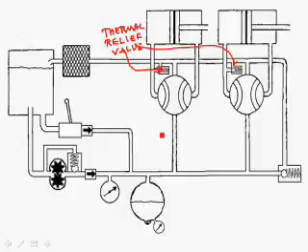Let's say that we park the airplane and these selector valves are in their current position and this is off. So no fluid can go through here, none can go through there, none can go through here. Well, just because hydraulic fluid is not compressible does not mean that it can't expand and contract with temperature. Let's say that it starts expanding because it's sitting on a hot ramp on a hot day in the desert. So the fluid in here starts to expand. The pressure is going to get higher and higher. It can't get out here, it can't go past this O-ring, and it can't go past the O-ring there either.